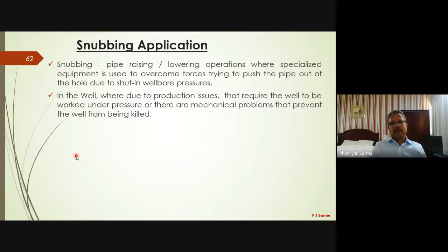In a conventional workover, the well needs to be killed, and a lot of the time the formation gets damaged, and even well recovery could be an issue. We face a lot of issues with well recovery and formation rectification. So with the help of snubbing, without killing the well, the workover can be carried out.